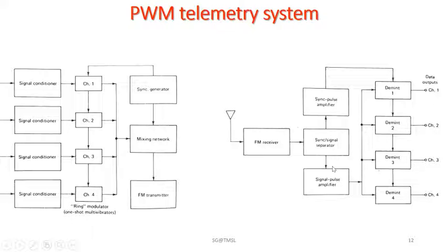where the synchronizing and the signal pulses are separated. The synchronizing pulse is sent only to the first channel flip-flop, while the signal pulses are sent to all channels' flip-flops. Now the synchronizing pulse turns on the first flip-flop, and the first signal pulse turns off the first flip-flop.